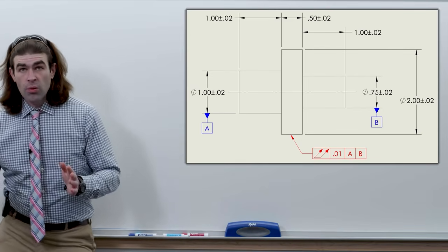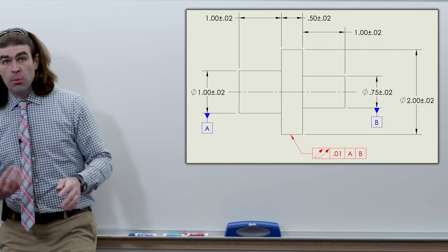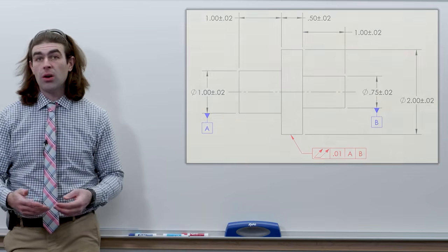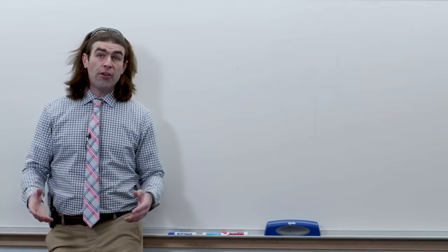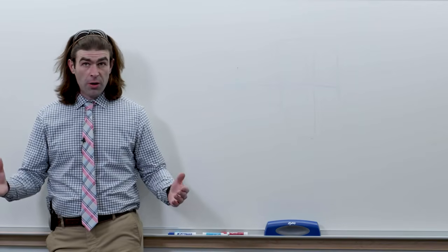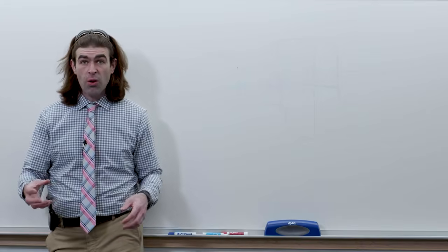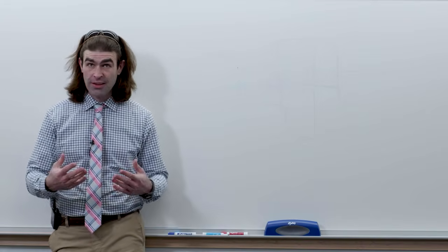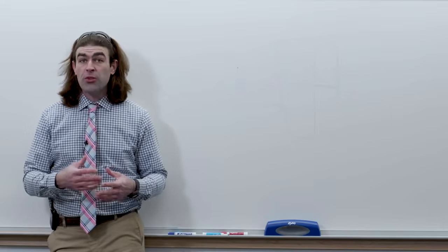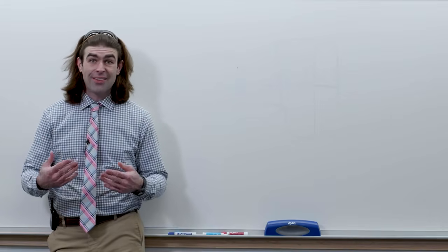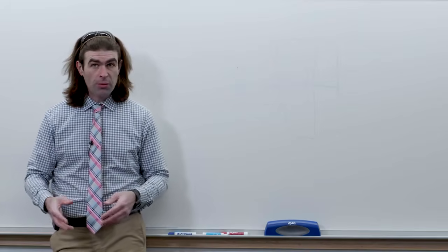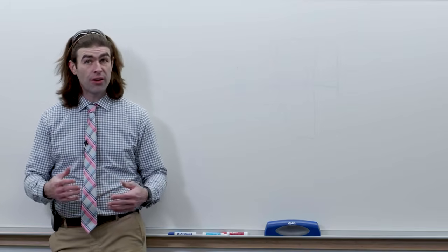Right? Neither datum is more important than the other. They could both be different sizes or the same size. This is often used with very long parts that you couldn't easily control with one datum. This can also be used with machining centers. So occasionally machining centers are called out as datums. They're not the best datum though, because normally machining centers are not very functional.